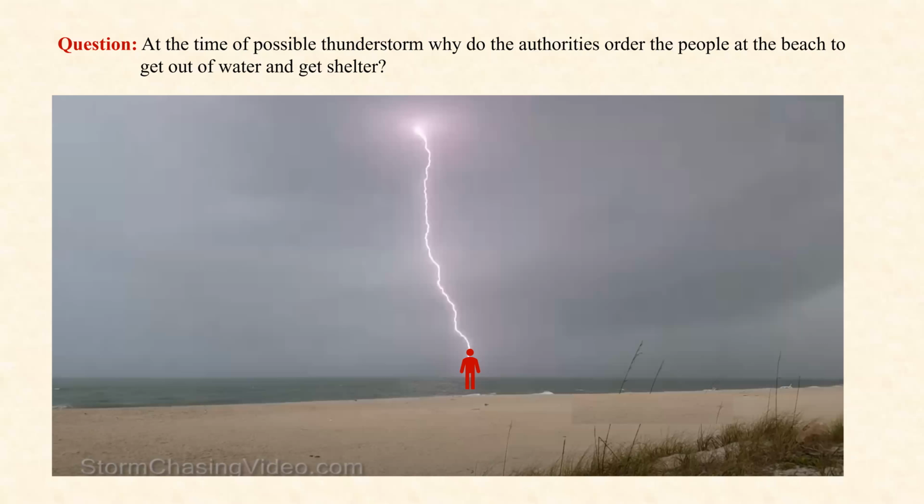Most of the time, that's not fatal either. We are going to talk about that because the current has to go somewhere. The current comes and it distributes like a hemisphere in the earth. And if you're too close to it, there's a potential difference across your body, and that gives you a shock, not the lightning itself. All right.